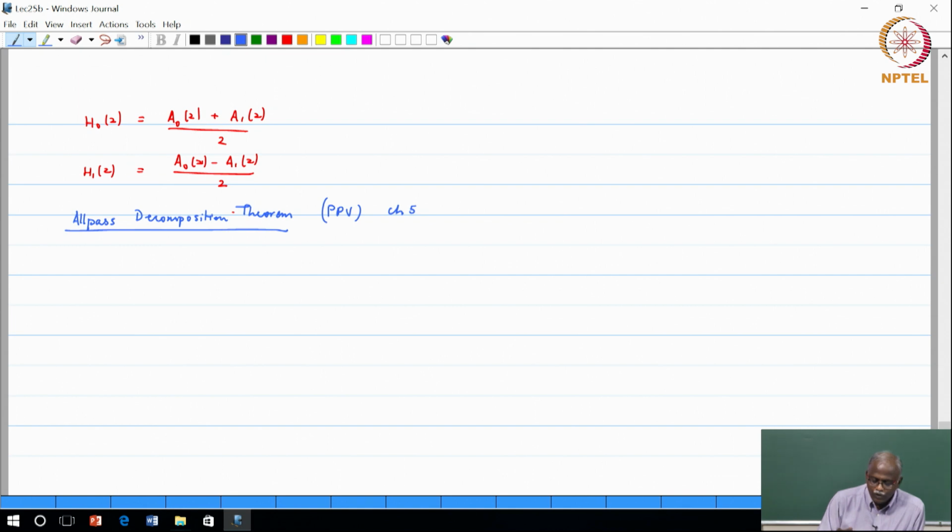So, what are we going to do now? We have studied all pass functions. We will now look at the solution that gives us a good set of filters H0 and H1, which can be used in an IIR 2-channel filter bank, and hopefully this gives us some clues to go beyond, because this one will have phase distortion.